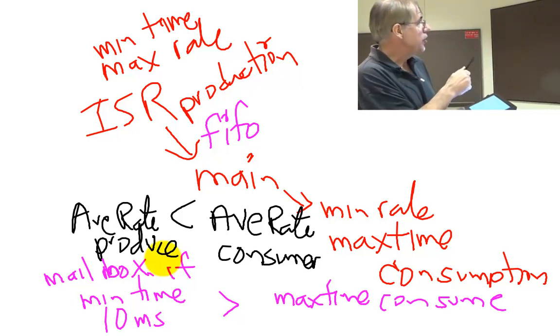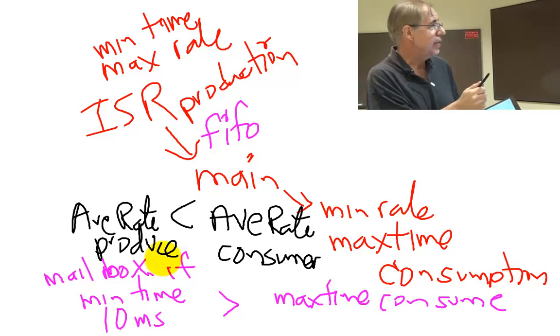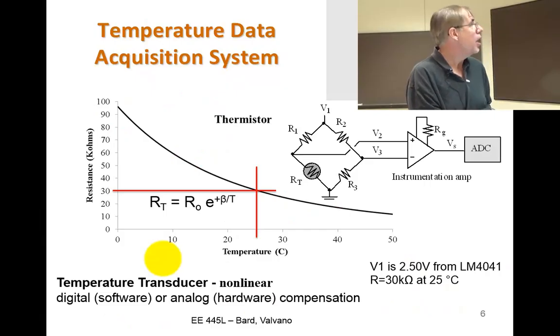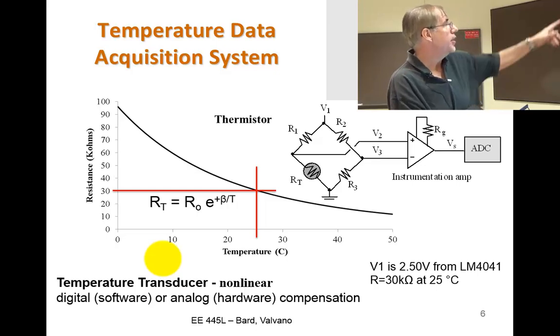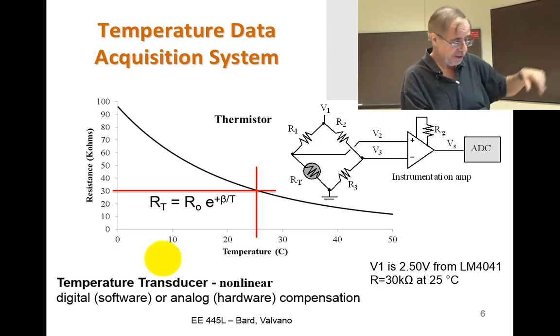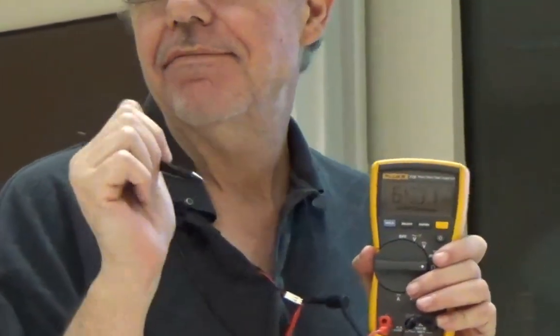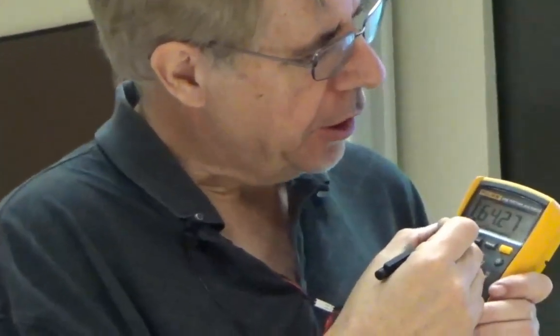Now, if the averages are bad, then it crashes and you can't get an answer. What I'm going to do is calibrate my thermistor. I'm going to get this curve. So what I'm doing is I'm going to do a 2-point calibration. I'm a mammal, so my body's pretty much isothermal. It's about 36 degrees centigrade in my axilla. So I'm going to use that as a temperature point. Can you see that? So we got to remember 64 point.